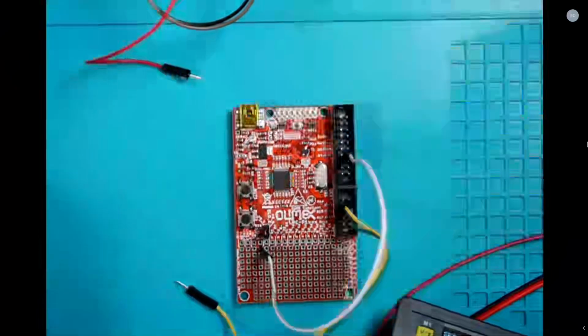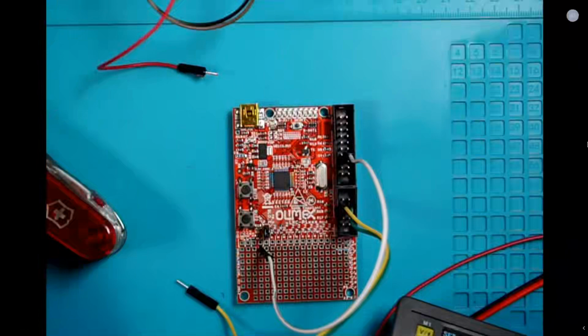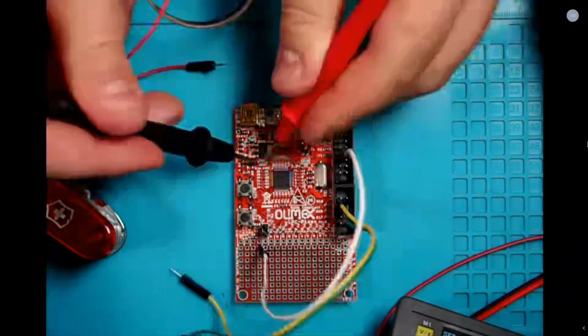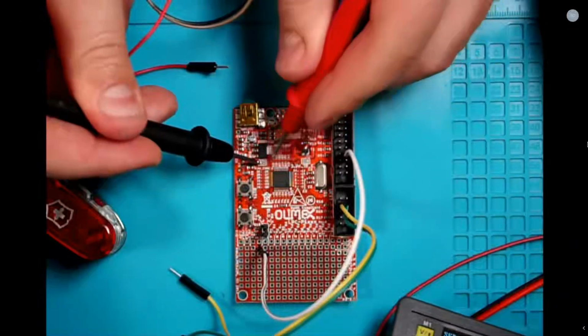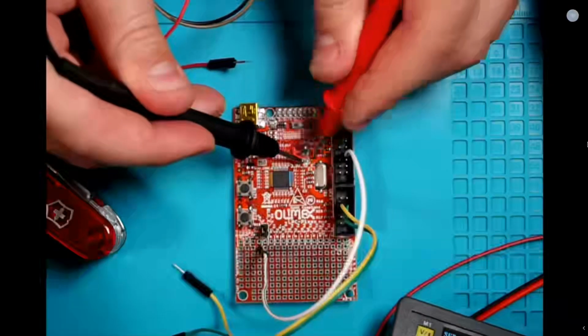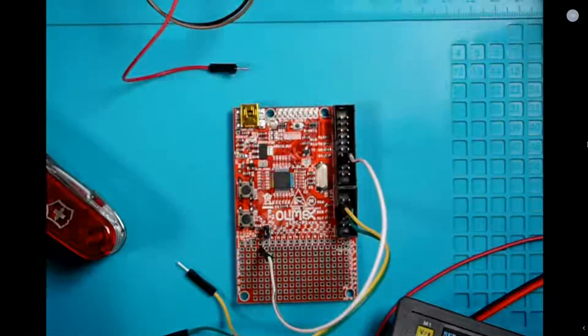So let's take a look. I'm going to leave the knife right there, and now let's take a look with our multimeter again. Let's make sure there's no more connection there, because now we'll have separated our power supply. So it sounds good. If I tap this, there is a connection, but if I tap the pads, there isn't. One more time. All right, we're good to go. So now we can actually solder two wires onto there and make all the necessary modifications.